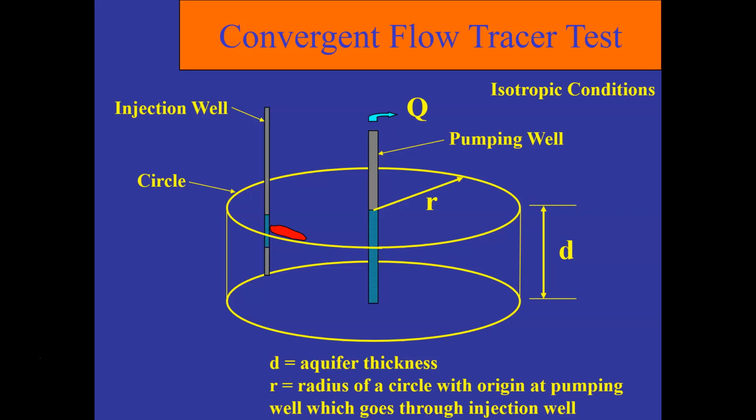So you might run for half an hour or an hour, and then inject into an observation well a suitable tracer. Just create a small cloud of tracer and have the pumping well pull that from the injection well to the monitoring well and observe its appearance in the pumping well. So you're not really adding that much to an aquifer test. You're doing all the transducer monitoring anyway. All you're doing here is adding an injection of a tracer into an injection well or a monitoring well, and then awaiting its appearance in the pumping well.